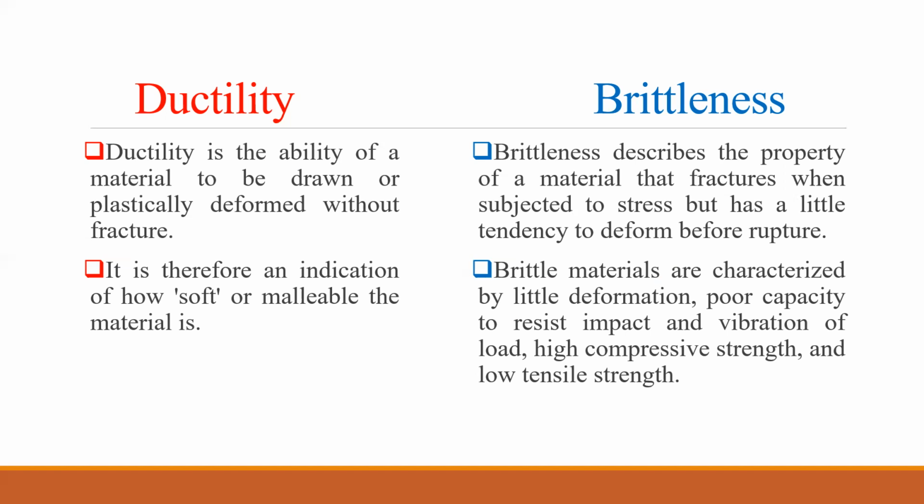On the other hand, if we take brittle material and apply tensile load, before fracture there will be no plastic deformation. The material will not elongate, and there will be no change in the dimension of the material. It will fail catastrophically, which means it does not give you any kind of warning or symptoms before fracture.